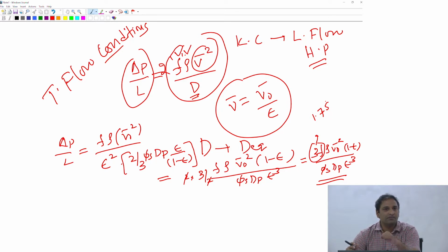They fill cylinders in the packed bed, they fill ball saddles, spherical balls, and make sure your Reynolds number is greater than 1000. We said for the flow of fluid around a particle, anything greater than 1000 up to about 200,000 was the Reynolds number range for which the conditions are turbulent.